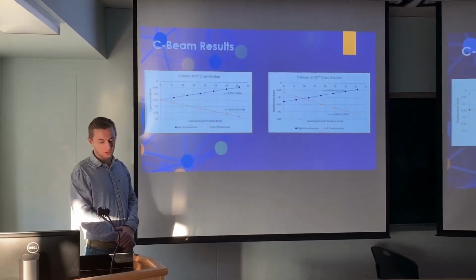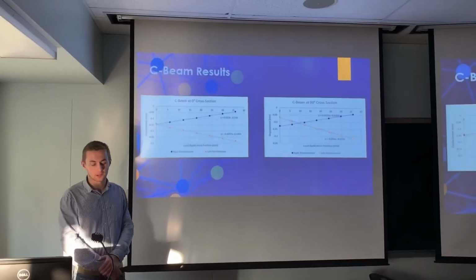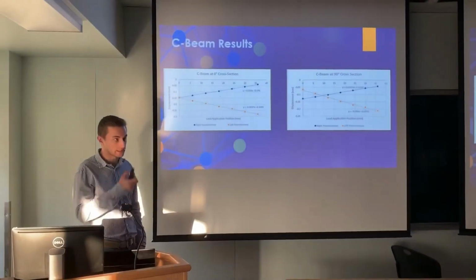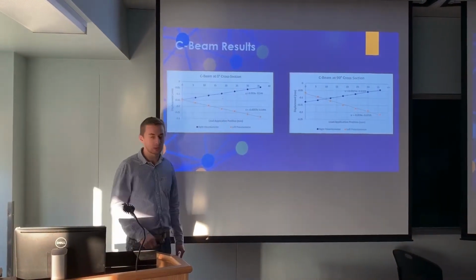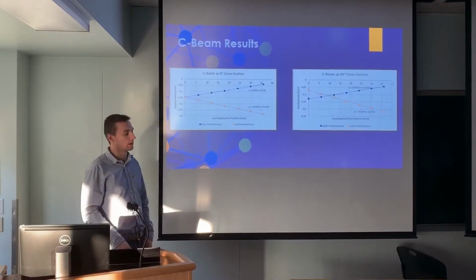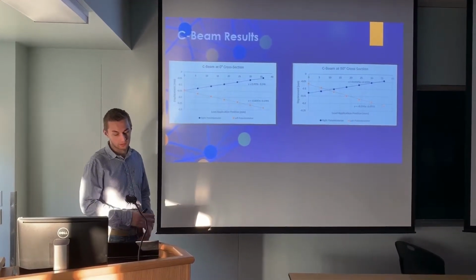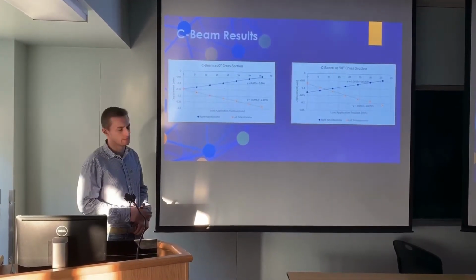In summary, shear center is the location at which the cross-section will not have a moment. That is why in this experiment, we tested the deflection on both sides of each cross-section at a variety of different locations. Now these are experimental results for the C cross-section beam.